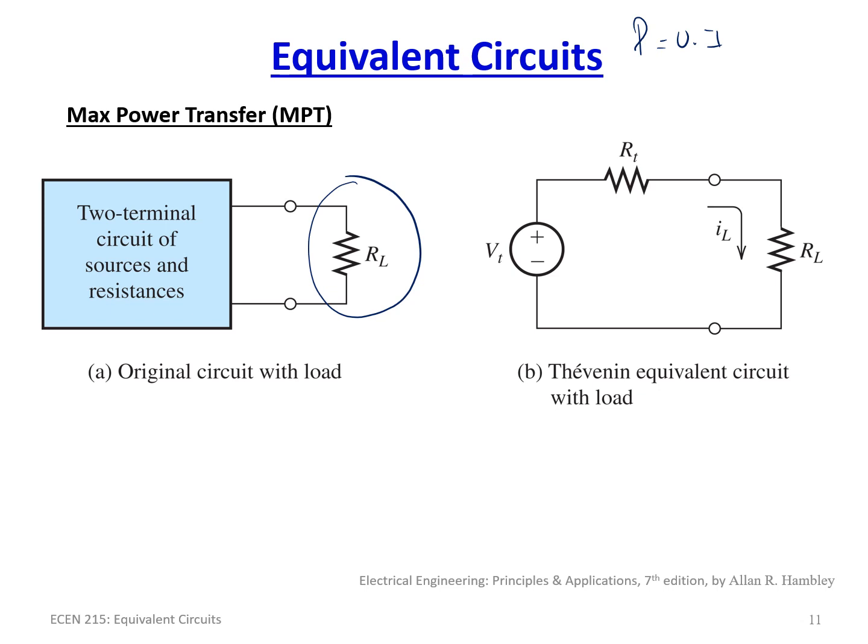So there's going to be a point where, for instance, if RL is equal to 0, then there's going to be no power in the resistor. You're going to short out the supply, but there is going to be 0 power in the load itself because the load is 0 ohms. And obviously another extreme of that, if RL is infinity, like basically open circuit, there's no current flowing through RL at that point, so therefore also power is 0.